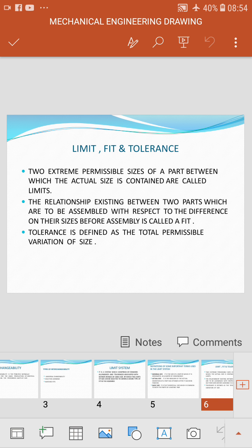For bilateral, the tolerances occur at both ends. In case of bilateral hole basis, it will be 25.025 mm high limit and the lower limit is 24.975 mm. It becomes 25 minus 0.025 equals 24.975 mm. The difference between high limit and low limit is called the tolerance.